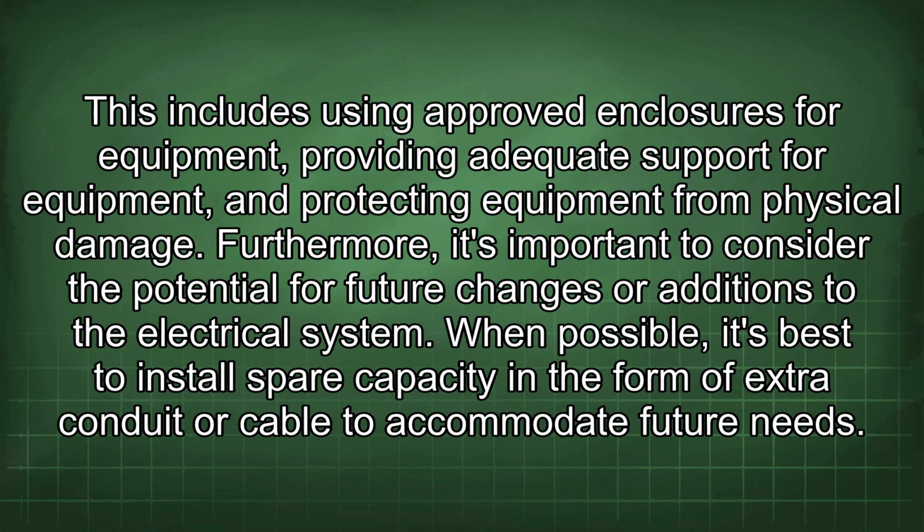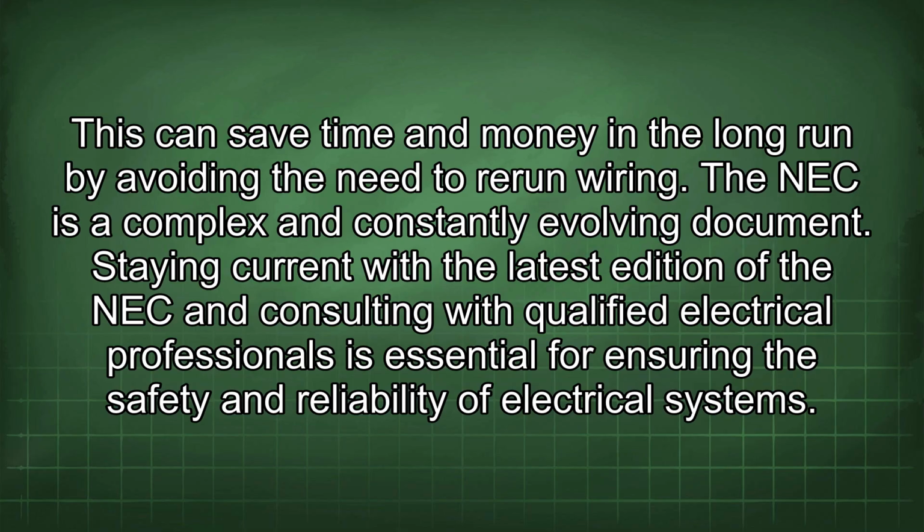Furthermore, it's important to consider the potential for future changes or additions to the electrical system. When possible, it's best to install spare capacity in the form of extra conduit or cable to accommodate future needs. This can save time and money in the long run by avoiding the need to rerun wiring.